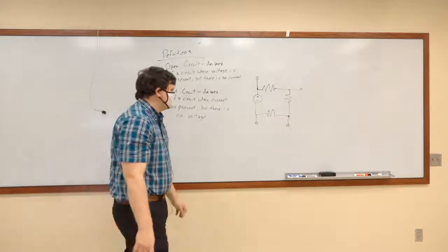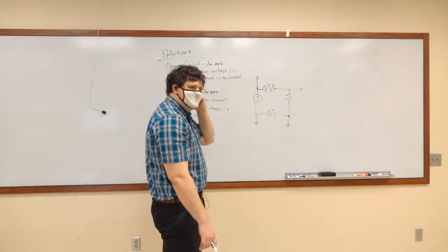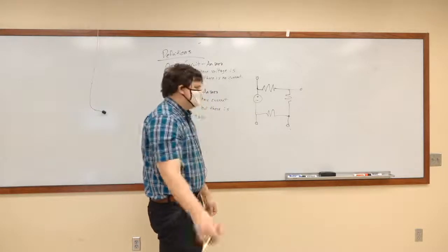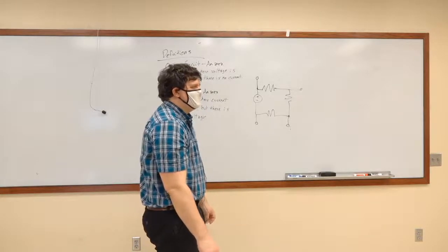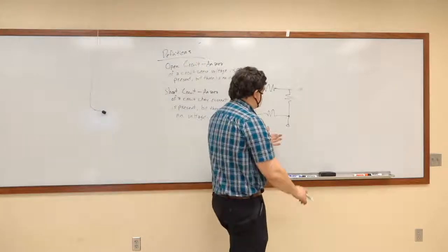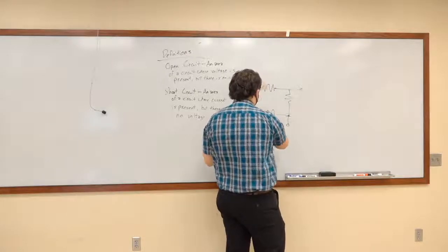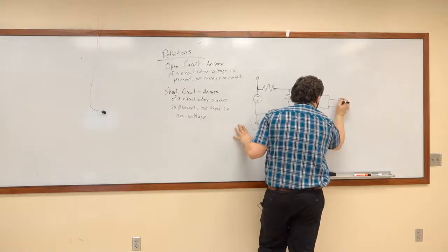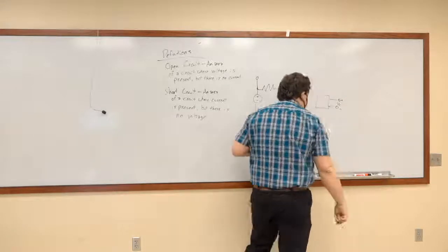And that equivalent resistance idea effectively comes to, Thevenin came up with the theory that you don't need to know what the rest of the system is. You could take any two of these wires, put the rest of the system in a box so that it's invisible, and have just these two wires sticking out, and all you care about is the voltage between them.